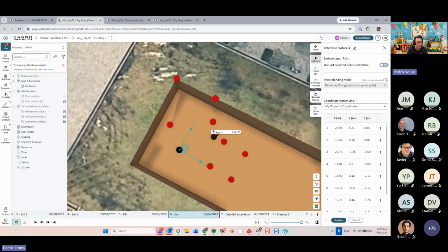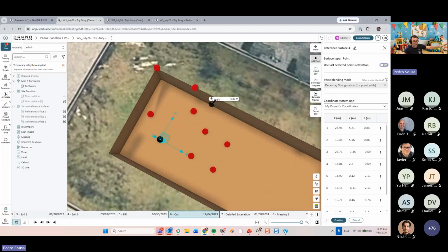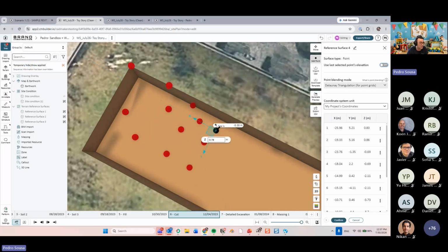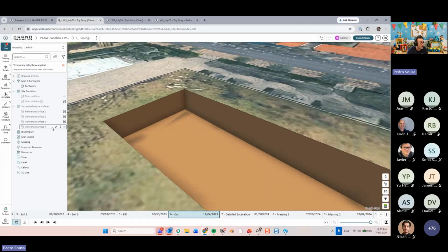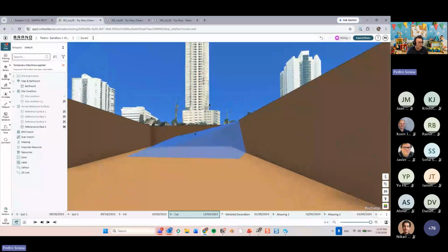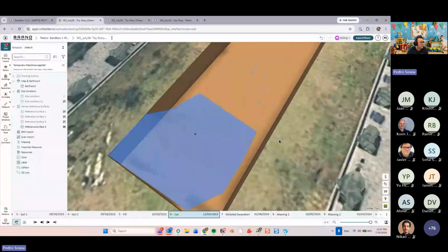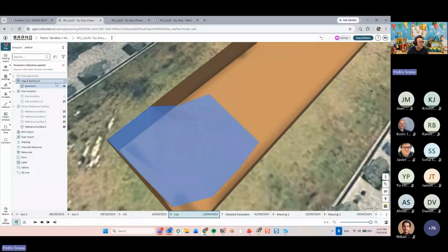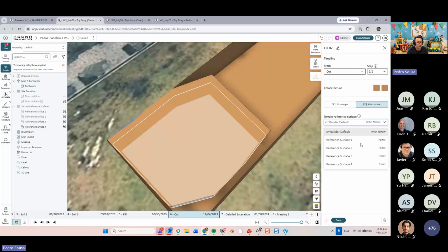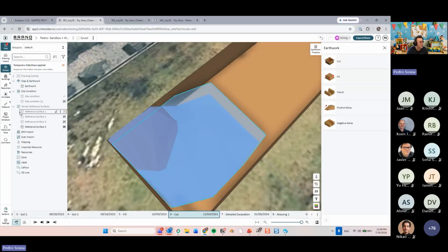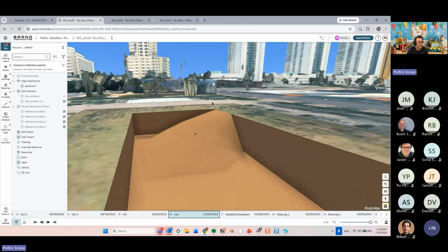And to make sure that I'll have a slope on the sides of the ramps, I'm going to go ahead and also place some points over here that are right on the ground, just to have a control point of where my slopes will be. Okay, so let's hit confirm. I got my surface over there creating that ramp, as you can see, and then very easily I can go in and add a fill, project the shape, hit confirm, follow the ramp, and then I got my curved ramp over there.